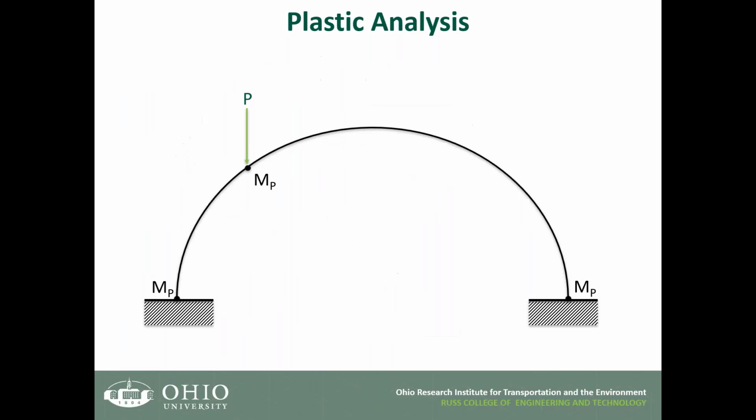So what's happening is that there's an interaction, based on those equations, between the plastic moment and the thrust. In most cases, the thrust is not very large in shallow cover. If the thrust is 15% or less, then for the cross-section capacity or the yield stresses, you just ignore it.